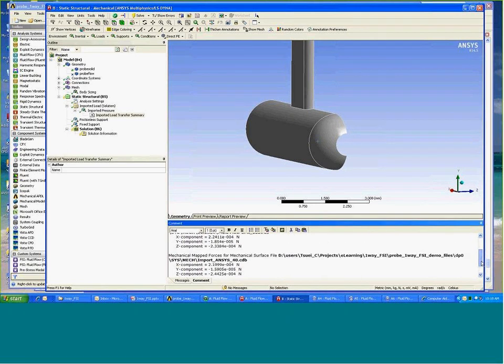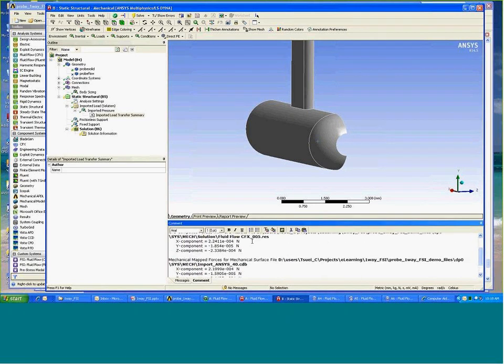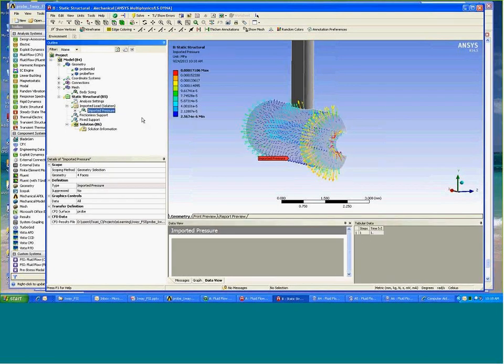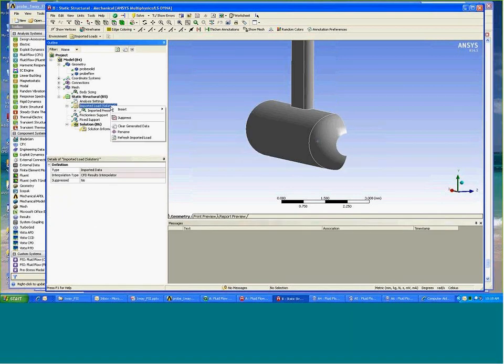And then you do see the force and load summary in three components, X, Y, Z components, for the probe surfaces. So in transferring load, I'm not limited to transferring just one surface. I can have multiple load imports. In addition to the probe surface, I have another component I'd like to transfer load for.